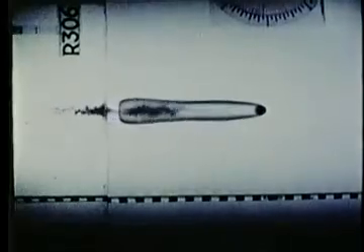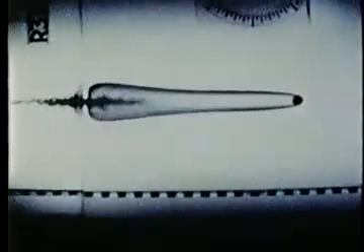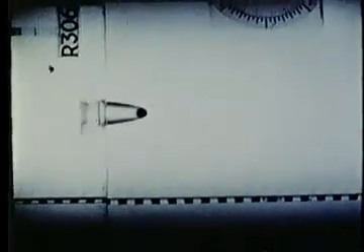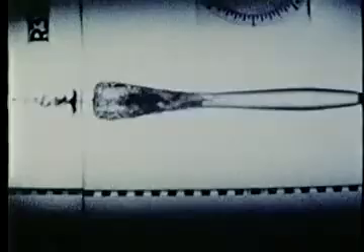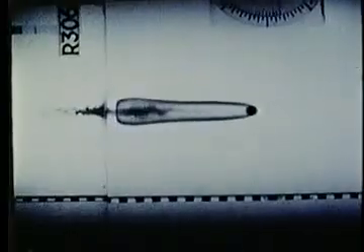Another type of cavity flow occurs when a missile enters water at high speed. In this sequence, a steel ball is shot into a tank of water. Here, the camera is turned so that the water surface appears to be vertical and the missile to travel horizontally. The cavity follows the missile into the water and eventually closes off, producing re-entrant jets which are seen here in slow motion. Initially, the gas within the cavity attached to the missile is air rather than vapor. Progressively, the air is left behind, and if the motion persists long enough, the cavity content will be vapor primarily.